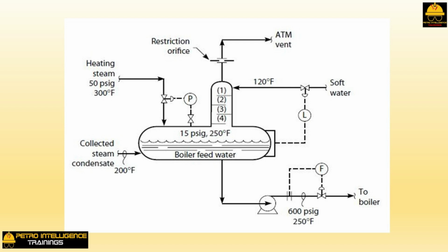Water carryover from the top of tray 1, as shown in picture, is simply a clear signal that our little 4-tray distillation tower is flooding. But what is causing the trays to flood? Trays usually flood because of excessive vapor flow.